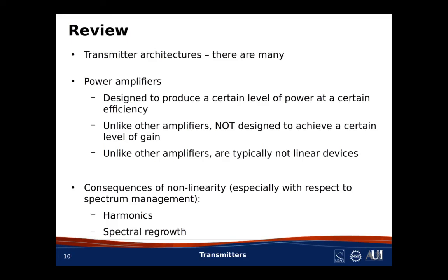Finally, we talked about the consequences of power amplifier nonlinearity, especially with respect to spectrum management. The two big issues for spectrum management are harmonics, which can usually be filtered to some extent, and spectral regrowth, which makes it harder to put signals close together in frequency.